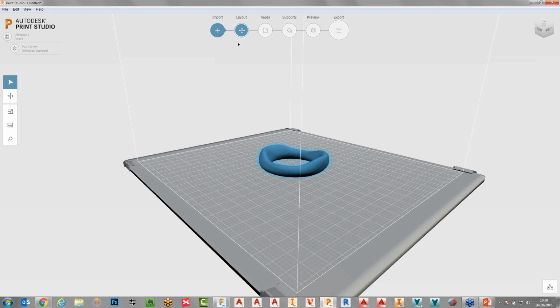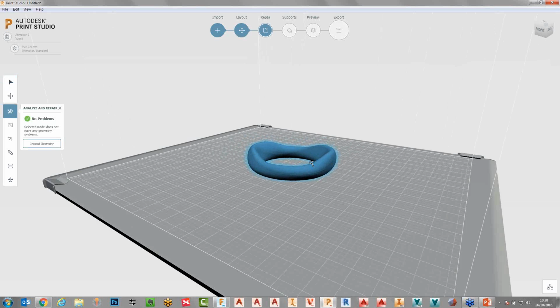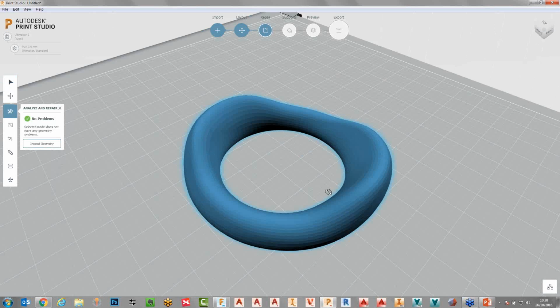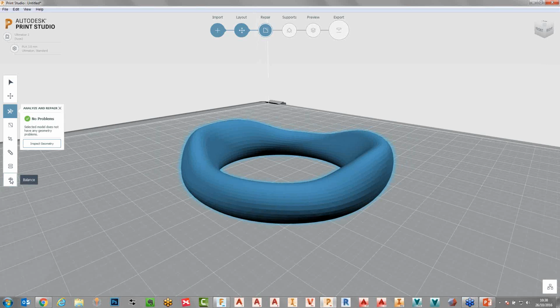Okay, I'm able to look at the layout with a range of tools for if I needed to scale design, measure, lay flat, things like that. If this was imported geometry, maybe not typically geometry that I'd created in Fusion, and there were some problems with it, I could start looking at patching holes and things like that. Because this has come from Fusion, there's no problems with it.